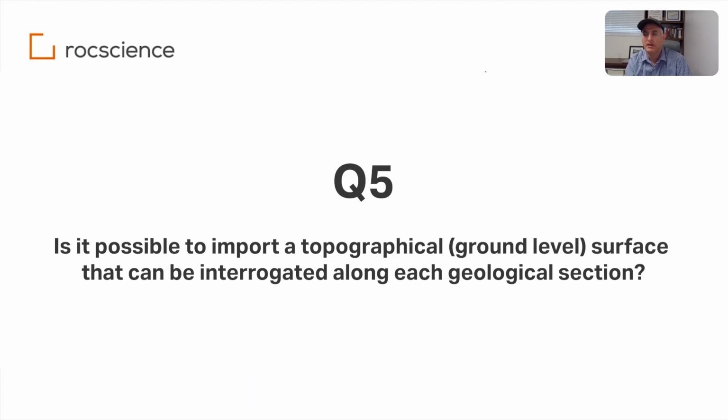Okay, the next question is, is it possible to import a topographical surface that can be interrogated along each geological section? Yeah, so as I mentioned, we're working on importing LiDAR data. We are also working on importing two other things. One of them is point cloud data, and the other one is importing CSV data for a collection of measured ground surface elevation points, so X, Y, and Z, and then we generate a mesh based on that data set.